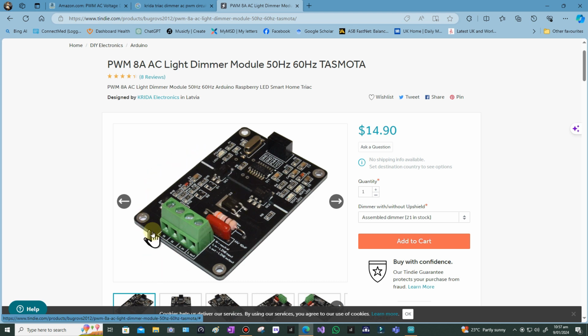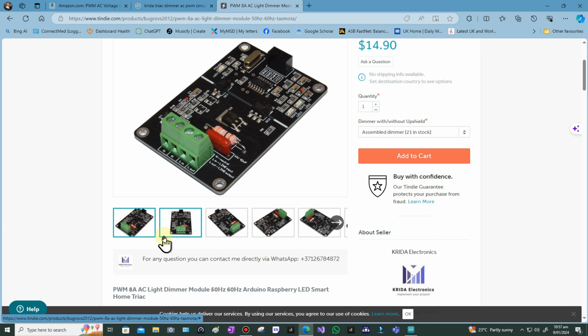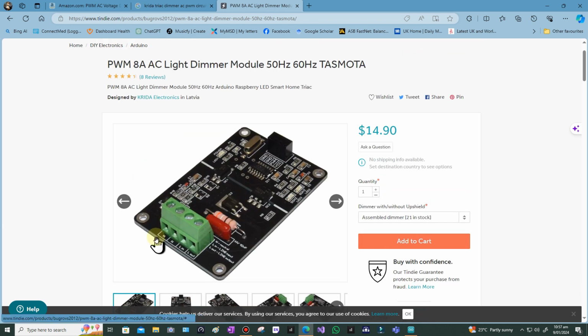So what I did was I put everything into a plastic box, and I mounted this thing with 4 nylon mounts and nylon screws. Everything is plastic, and I kept these wires from being pulled out. They're mains wires, and I used special connectors to stop that happening. Otherwise, you can give it a tug, and then you've got a live wire coming out, which I can show you in the demo. So this you can use on a whole range of micros, or Raspberry Pi, whatever. I'm using the ESP32.